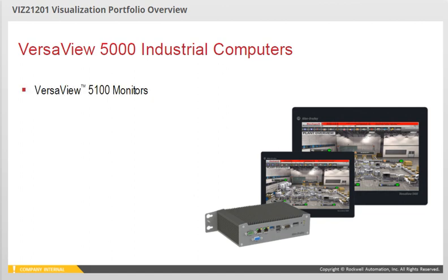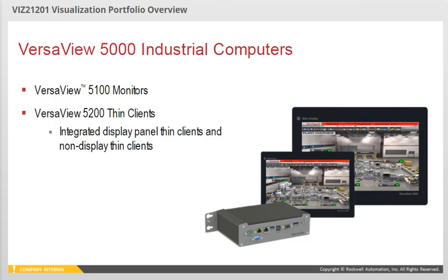The VersaView 5100 line of monitors are industrialized monitors with no integrated computer. These would connect to a separate computer in a panel. The VersaView 5200 thin client is a line of thin client computers, either with or without an integrated display. They are designed to integrate with Thin Manager software, a Rockwell Automation server-client solution that provides efficient centralized management and dramatically simplifies system maintenance. The VersaView 5200 thin clients running Thin Manager software are ideal for the HMI terminal clients